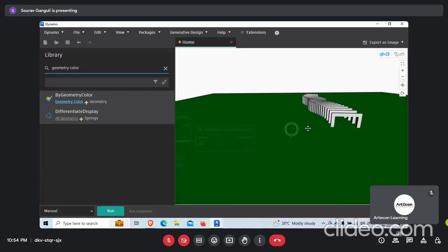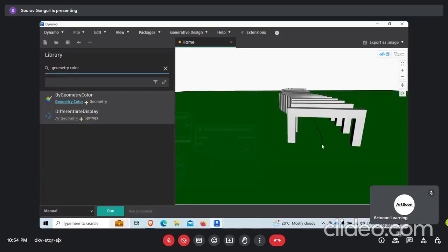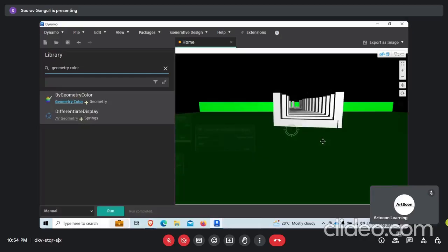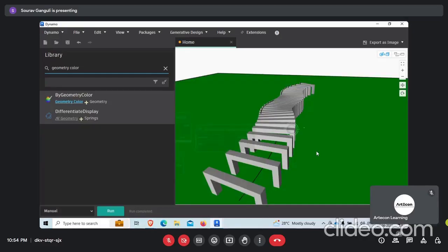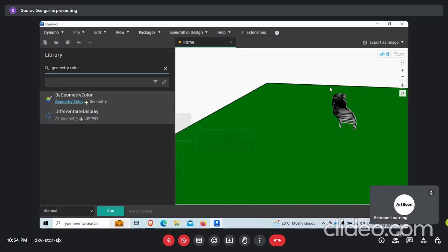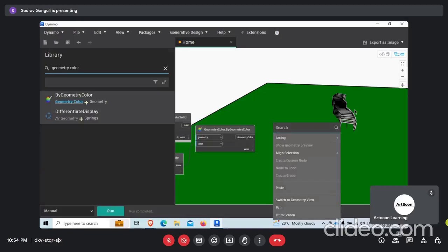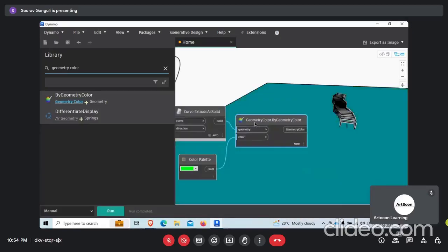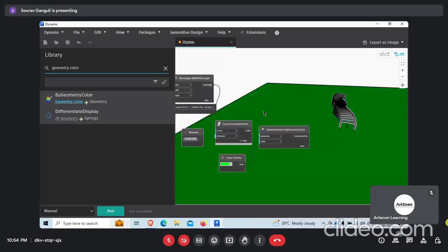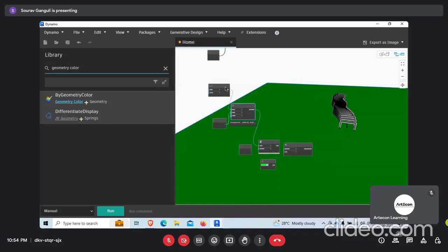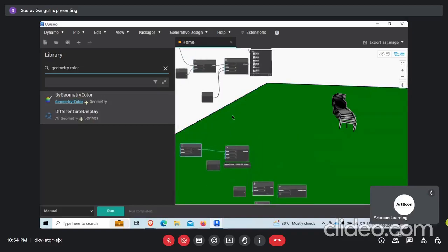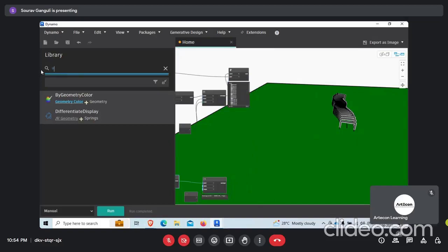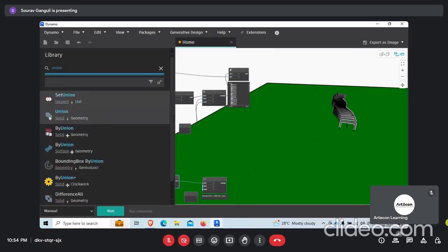So as you can see, the walkway that we have over here is half below the ground plane like this and half above it. So what to do? We need to make sure that we only have the path which is lying above the 0,0 portion of the work plane. So what we'll simply do is, we have the solid over here as the ground plane, we will do a solid subtraction. For that, we will take all the solids and join them into a single one, which is the union command.